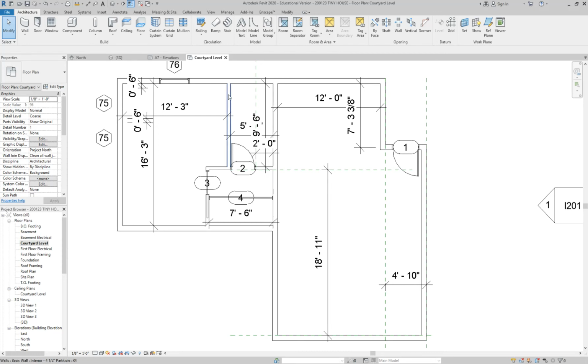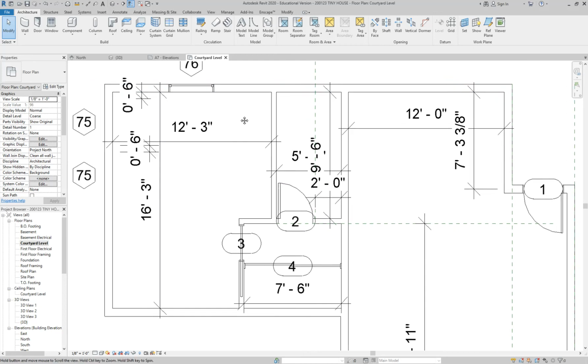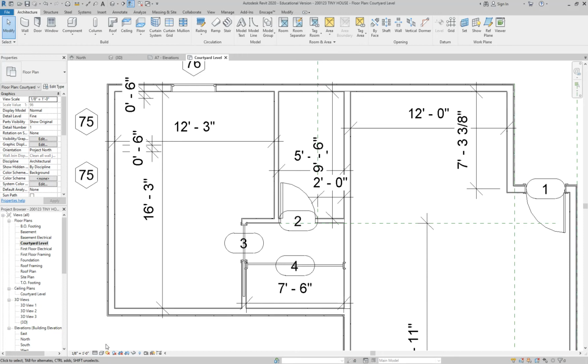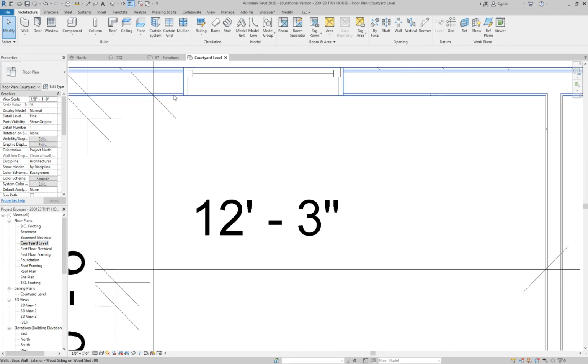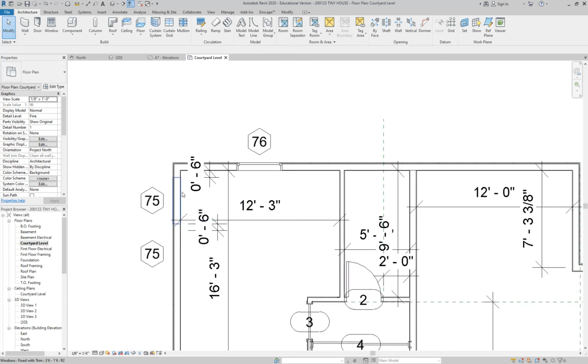Probably coarse, right? That's okay. So you can always cheat and come down and take a look at these. So you knew it was one on the ends, right? So how could you guys tell that mine was set to coarse? Yep, it lacks detail. So if I go to medium or fine, you can see that now I can see the drywall, I can see where the stud cavity is, sheathing, and then I think this is wood shingles. So you can start seeing the details.